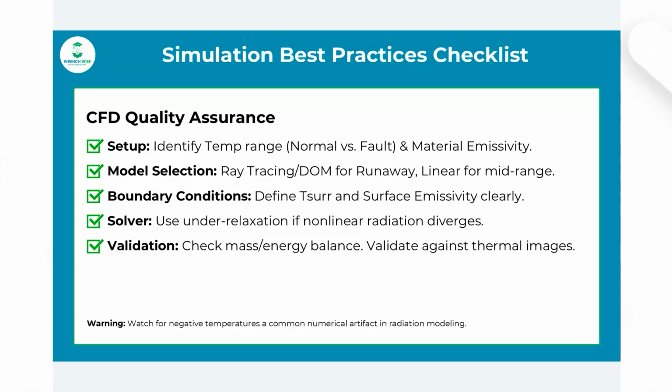Ultimately, coming down to boundary conditions themselves, radiation sort of connects everything. Therefore, the surrounding temperature is just as important as the temperature of the battery itself. If you leave the environment undefined, OpenFOAM might assume that everything is at 0 Kelvin, which will just suck all the heat out of your system instantly. So define your surroundings, or at least where your battery is situated. What is the temperature there? Keep it very clear there.